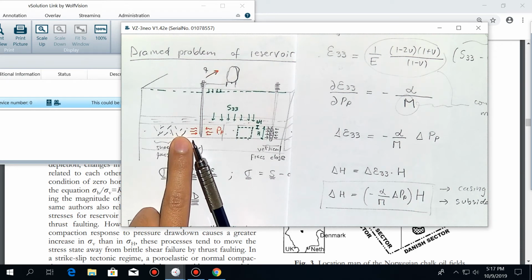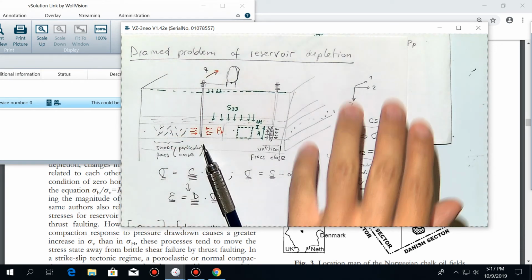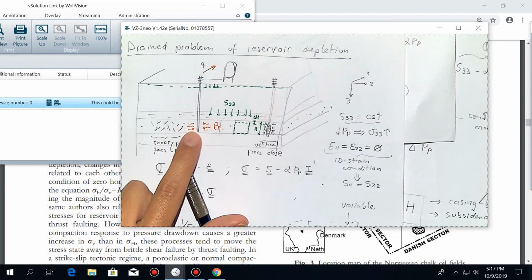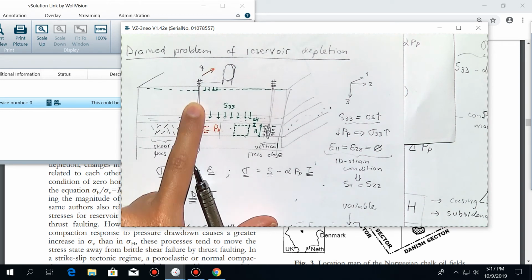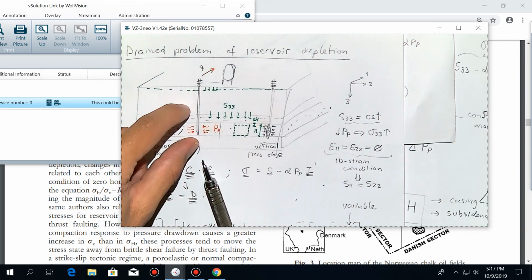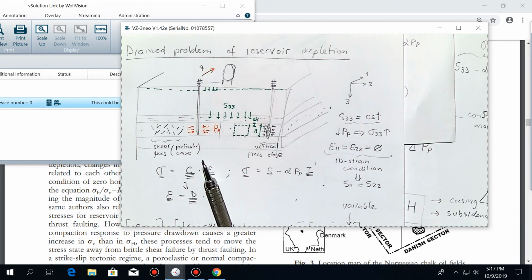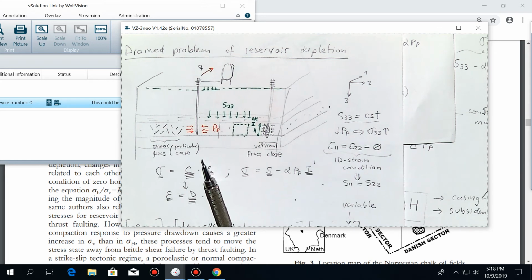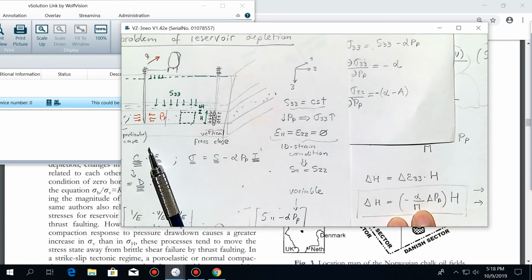If you have a shallow formation, then the strains in the reservoir are going to propagate more easily to the surface. But also those reservoirs were relatively soft carbonates with a very thick thickness. So they were very thick reservoirs.